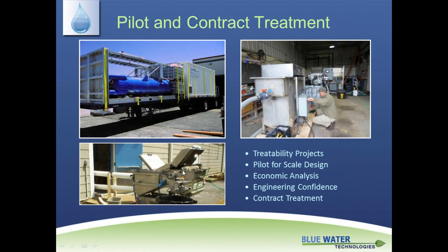It's an ultrafine screen for capture of total suspended solids, typically more in the fibrous solids, agricultural, food processing, municipal markets as well. What we're going to be talking about today is really going to hinge on this family of equipment. This is our Centraflow filtration brand, and within it we use our Blue Pro adsorptive process for removal of metals and nutrients. We can also do biological treatment within those vessels as well.